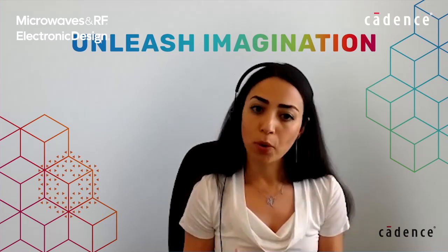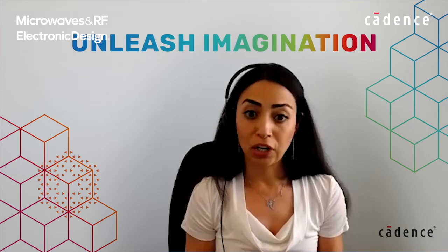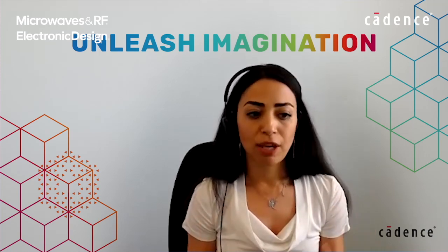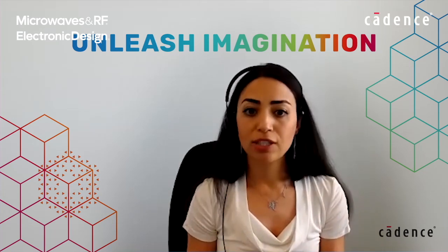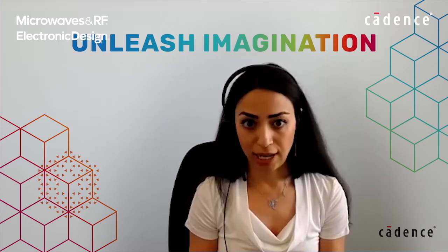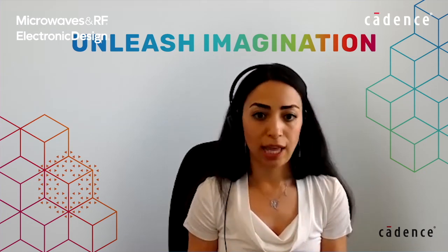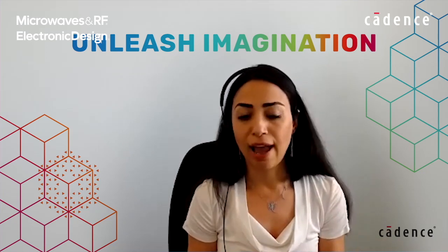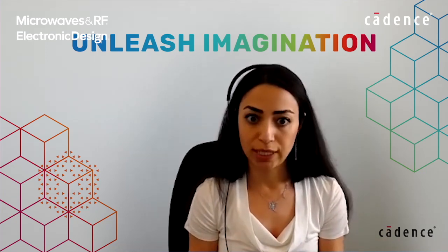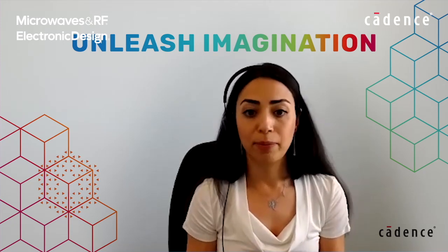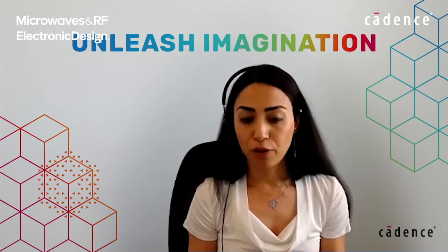So it's so important to address all these thermal issues in early design, especially for a chip, for example, because when you have a chip and you know exactly where your hotspot is, you can put your temperature sensor accurately, and then you can monitor that temperature sensor. For a chip, for example, what are the thermal optimizations that they can have is reducing, for example, the frequency. And if they know exactly where the hotspot is, then they can have perfect mitigation algorithm for their chip.